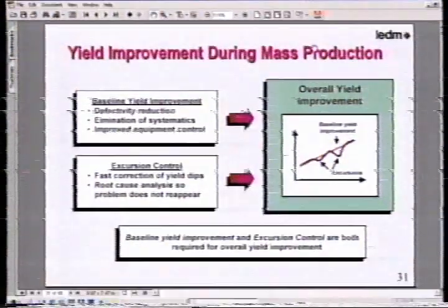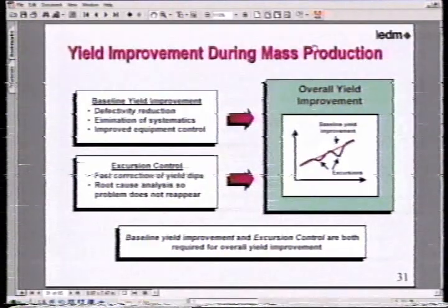So you can see what has happened is the characterization monitors have been able to pick this up early and drive this down toward the target D0. And this is what the characterization monitors and doing the yield modeling that I'm talking about, looking at the process design interaction, lets you do. I don't want to say that everything happens before you send the process into production. A lot of it does happen during the production.